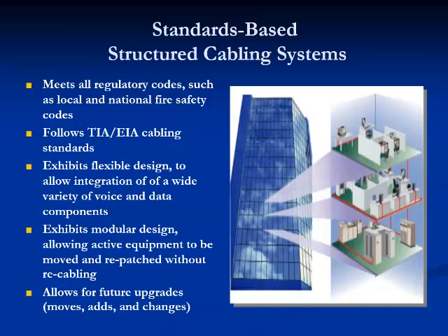Now, an ideal standards-based structured cabling system must address the following design criteria. First, it must meet all regulatory codes, such as the local and national fire safety codes. It should follow TIA/EIA cabling standards. It should exhibit flexibility in its design to allow integration of a wide variety of voice and data active components.